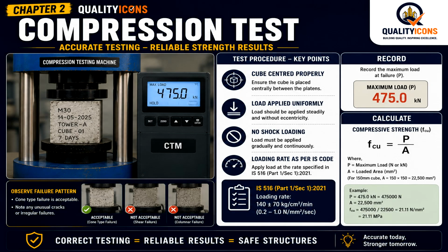After the curing step is completed, coming to the compression test. Compression test means CTM. This is the laboratory test called CTM. CTM means compression testing machine. The compression testing machine measures the concrete compressive strength of the cube.